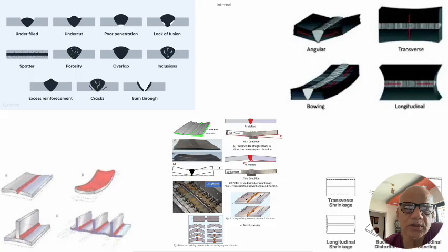Porosity most of the time is internal, very rarely, or sometimes you can see it on the surface also, open to the naked eye, and you can correct it. But surely an experienced welder can see the gas which is bubbling into the weld pool, and if it is having a very aggressive action there, then porosity is surely going to come.